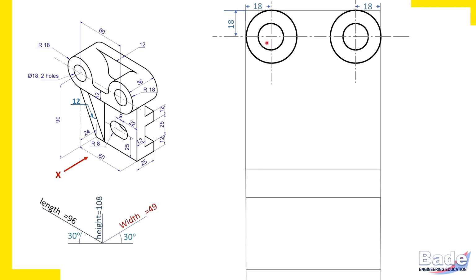Now these two cylinders will appear rectangles in the top view. And third dimension for the cylinders. For example, this cylinder. This is length of the cylinder, width of the cylinder. This is the height of the cylinder, in fact. And width of the cylinder is 30. Width in the sense dimension of the cylinder parallel to width axis. That will appear vertical in the top view. So this 36 mm dimension will appear vertical. So from front you should measure 36 vertically.